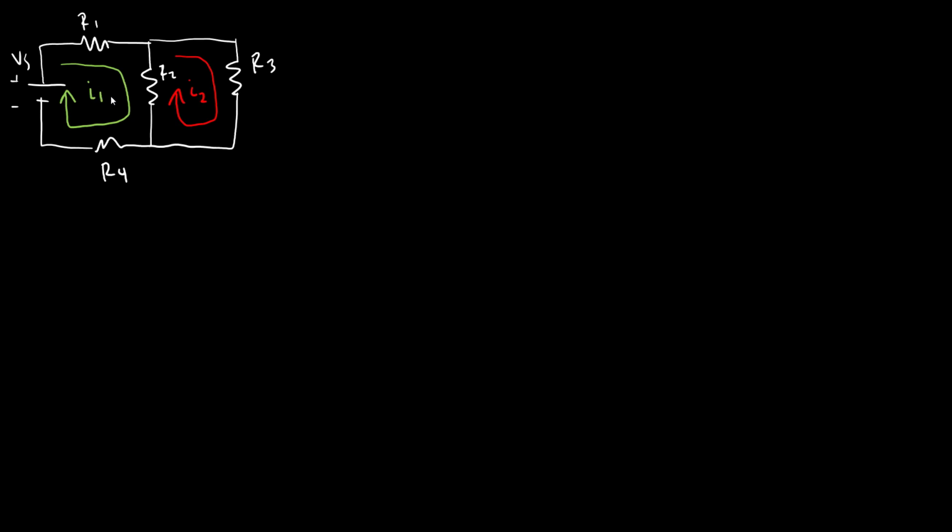This always confuses people when they see this and you go, okay, so you have mesh current I1 flowing in this loop and mesh current I2 flowing in this loop, but they're going the opposite direction through R2 here. So does that somehow mean you actually have electrons flowing in 2 different directions through R2, or 2 separate currents flowing opposite each other? No. R2 still just has a single current flowing through it that we will solve for later. I1 and I2 are just variables that we are making up that will make solving this circuit a little easier. Now, conceptually, that's very hard to understand at first.